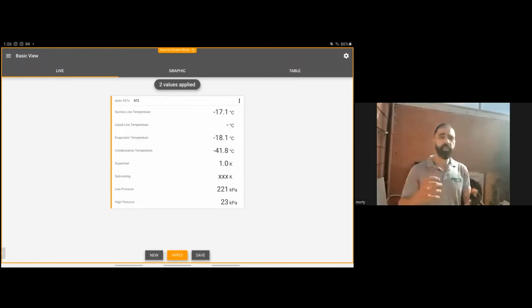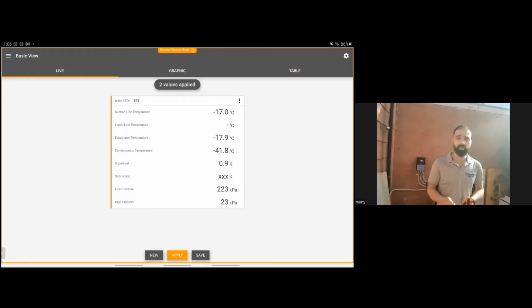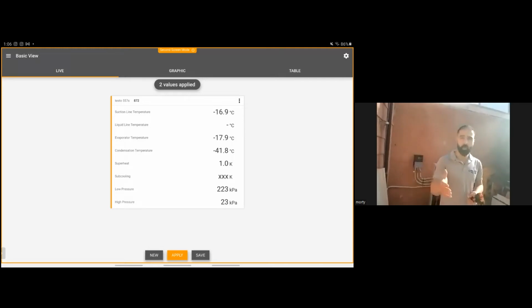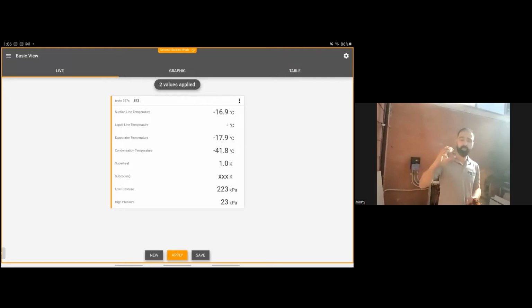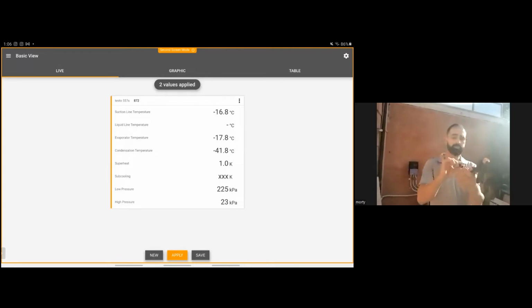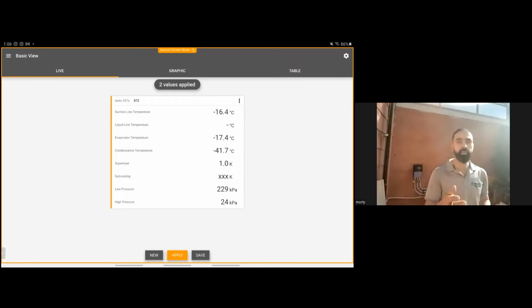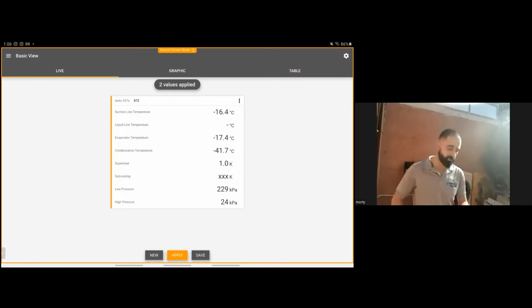What happens if you don't insulate the bulb at the exit? If your case is at 20 degrees and you've got air hitting the bulb, what will happen? As I mentioned earlier, the bulb will be affected by the room temperature, not by the pipe temperature. Therefore, it will flood. If you have it insulated, it's not affected by the room temperature, so the TX valve only feels the exit temperature of the coil.